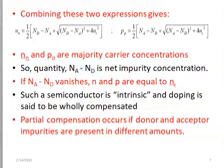So in a situation where Nd minus Na or Na minus Nd is equal to 0, it means we don't have any net dopant, and therefore it is purely an intrinsic semiconductor. Such a semiconductor, as I've already said, is intrinsic, and the doping is said to be wholly compensated, meaning the doping has no effect in this case. Or even if you introduce acceptors and donors of the same magnitude, one will cancel out the other, and the semiconductor will start behaving as if it is an intrinsic semiconductor.